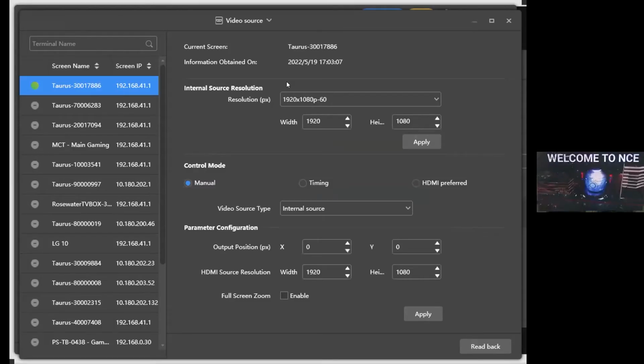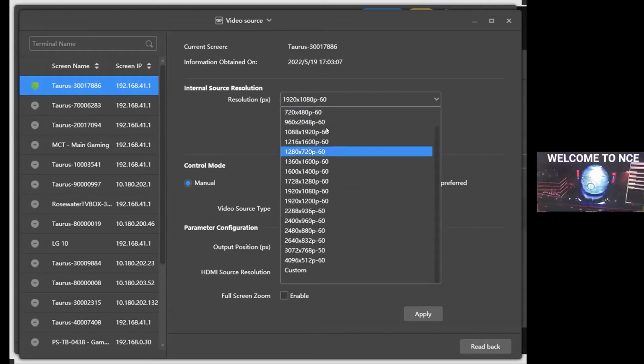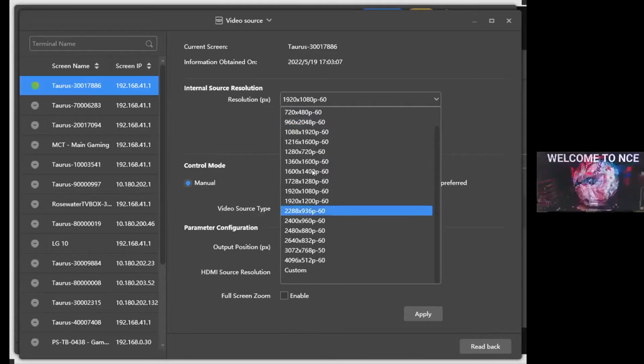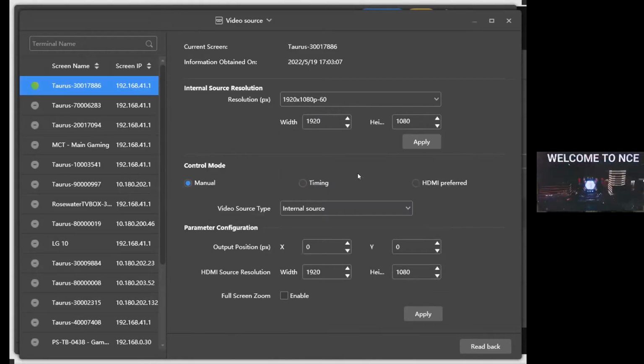But when you configure the screen connections interface, the system tells you it can't send your resolution to your LED screen. It notices you need to change the video source input. The resolution here, whether width or height, needs to be bigger than your LED screen resolution.